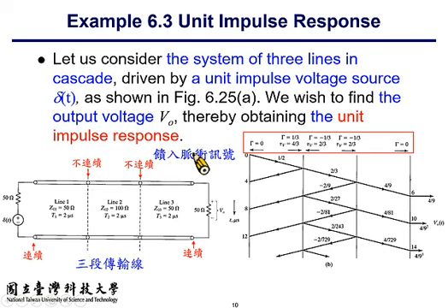So the gamma is what? Sometimes we write gamma 1 2, meaning looking from section 1 to section 2. Looking from 1 to 2, we put 100 minus 50 over 100 plus 50. So gamma 1 2, the reflection coefficient at the first interface, is 1/3.